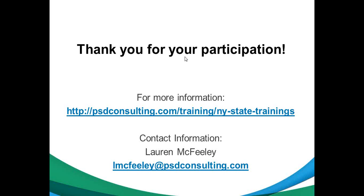Again, you set it up once and you get the data out once. You set up your eCam. It's an Excel tool, or Excel VBA code built into an Excel environment. You set it up once with these trends, the series of charts that you're used to looking at. You figure out what the issues are. That's going to take you the majority of the time. To repeat this process next quarter or a month down the road is going to be a fraction of the time getting the data out of the BAS, because you've already done it once. You've already got the trend historian set up. It's just getting new data out of the system.